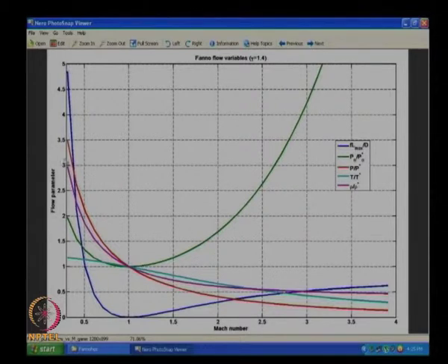If I think about 5 meters at say 0.2, 0.3 Mach number, from there it is going to 4 meter, 3 meter, 2 meter and 1 meter. It travelled 4 meters for that particular f by D till it became 0.5 Mach number. I started at 0.3 and it ended at 0.5 while the tube was 4 meters long. If I go 1 more meter, it of course is going to reach Mach 1. When I go closer and closer to Mach 1, this flow is very sensitive to the friction. Till that time it is not. Subsonic flow is not at all sensitive to it.